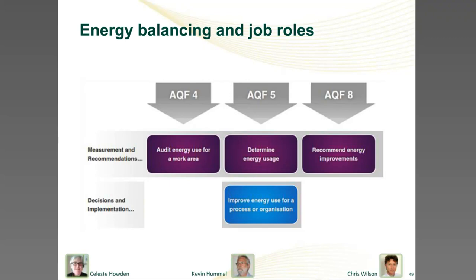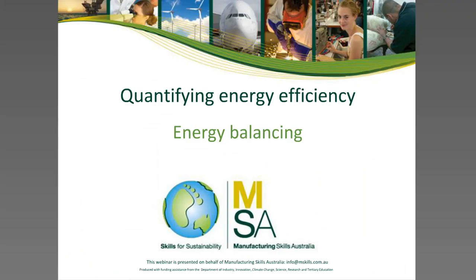This complexity is much greater than the others. And so typically, if you're doing a combined mass energy balance, say you're cooking biscuits, the mass of biscuit going into the oven is greater than the mass of biscuit coming out. So you'd need to do a mass balance first to work out how much water was lost, then look up your steam tables to work out how much energy that is, and then you do the rest of the energy balance.